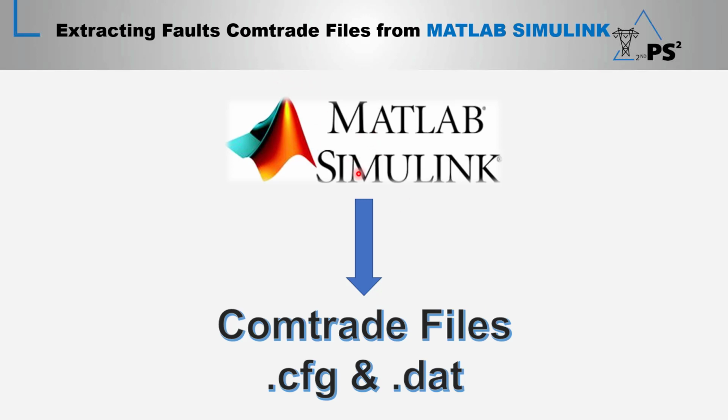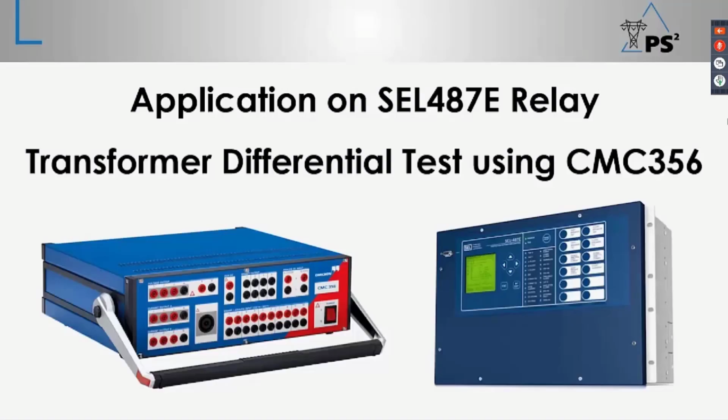Thank you. Now we will go back again to Engineer Muhammad Rashad. He will talk about this point clearly. Thank you, Engineer Hani. And now let's see how to replay the fault that Engineer Hani extracted from the MATLAB Simulink as a Comtrade file, using Test Universe 4.3, in order to replay the fault using our test kit CMC356 on the SEL 487E relay.